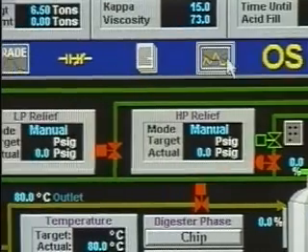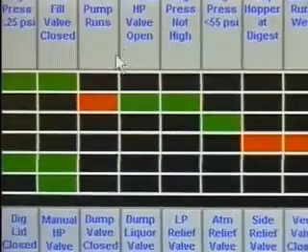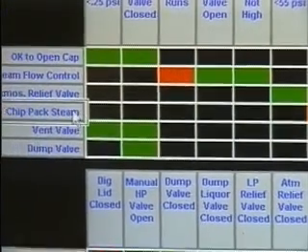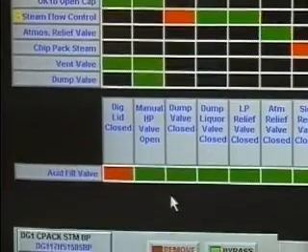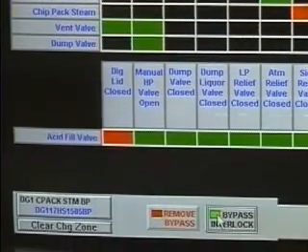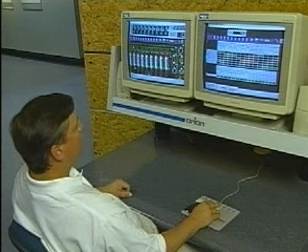Now, let's look at the interlock display. It's important to point out that not only does it provide a tabular type of interlock depiction where we can see what is being held out of sequence, but also with password protection, we can select a particular element and put a bypass around it. By setting a bypass around it, we can then see an indication on the valve.